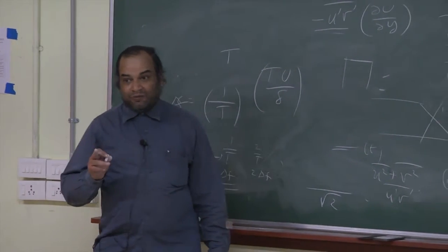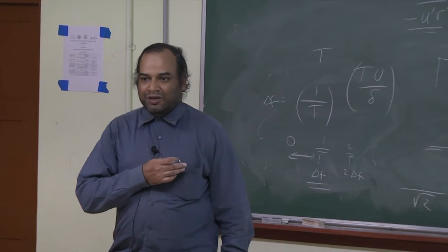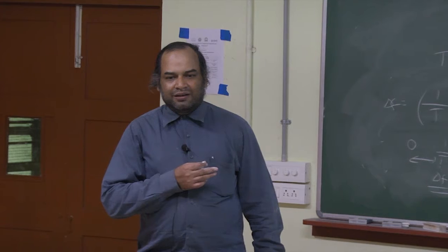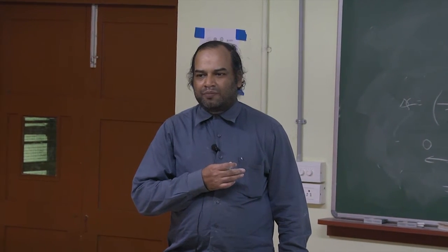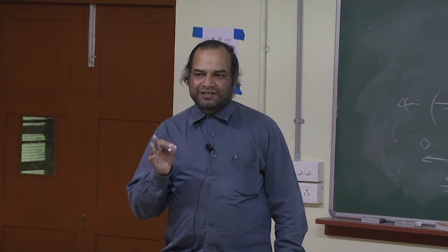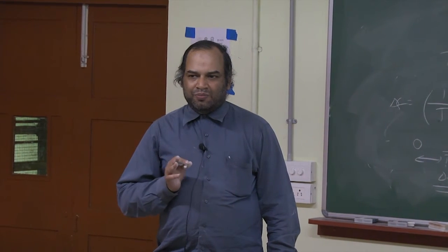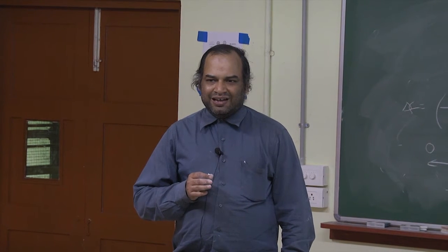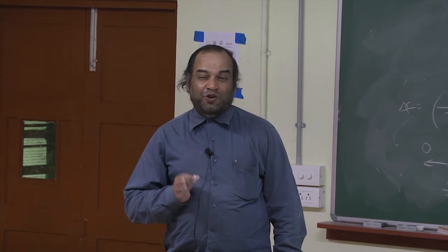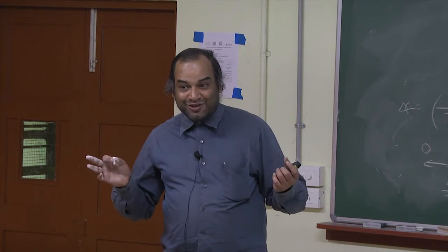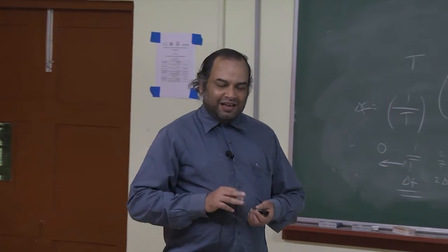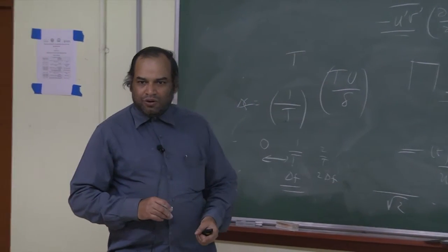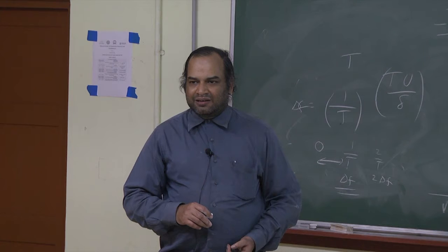For the spectrum, if you really want the controversial spectrum I told you about, k minus 1, typically I ask my students to do it for at least 1.5 to 2 minutes minimum. I know some Australians who do boundary layer measurements in a tunnel, which is overkill. Actually they do it for 45 minutes. The conditions might also change, but I think that's madness. Anyway, this should be very large indeed if you want to get a nice average. Okay?